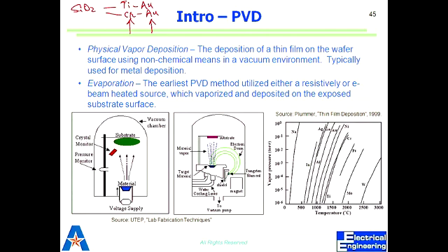Once I see a stable change in thickness of whatever is reaching, I open the gate. Now material starts going to my wafer. I'm measuring how much is getting deposited, so I know my thickness as it develops. Once I get to my desired thickness, I close the flap, reduce the heat or E-beam, and I'm done.